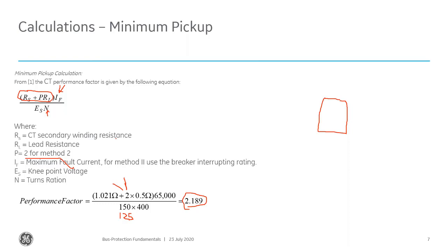So there is some place where you need to make up all of those CT circuits into a summation. Now, one of the guidelines that they always say is you try to keep the leads for all of the CTs about the same. So that's one of the reasons that in a switch yard, you might have this paralleling cabinet. Let's say you've got a bus like this, so the breakers are coming off the bus some way like this, and your switch house is sitting over here.